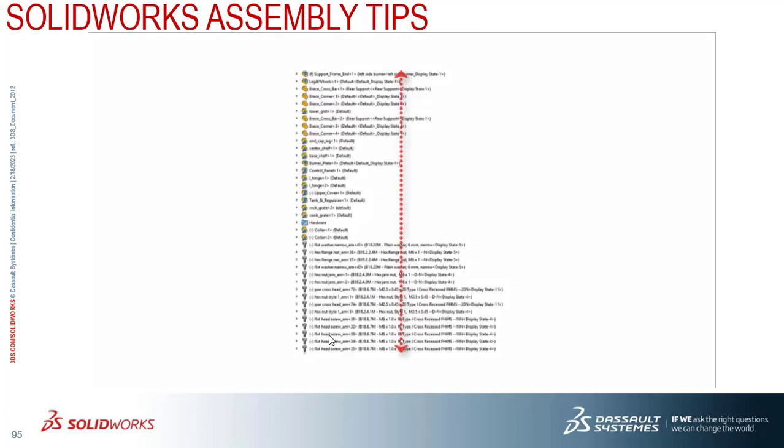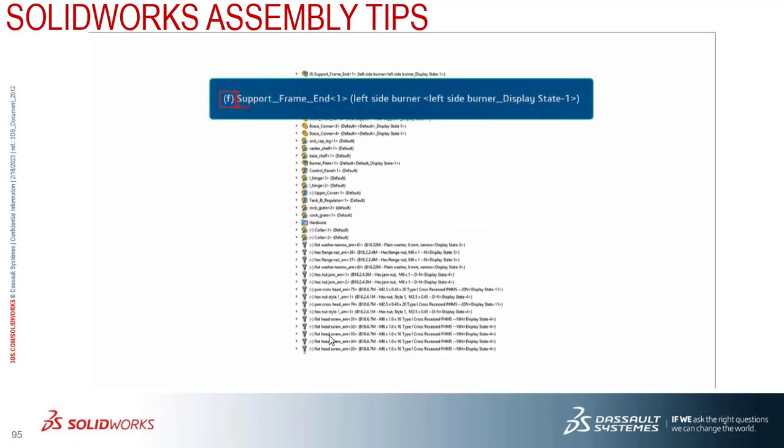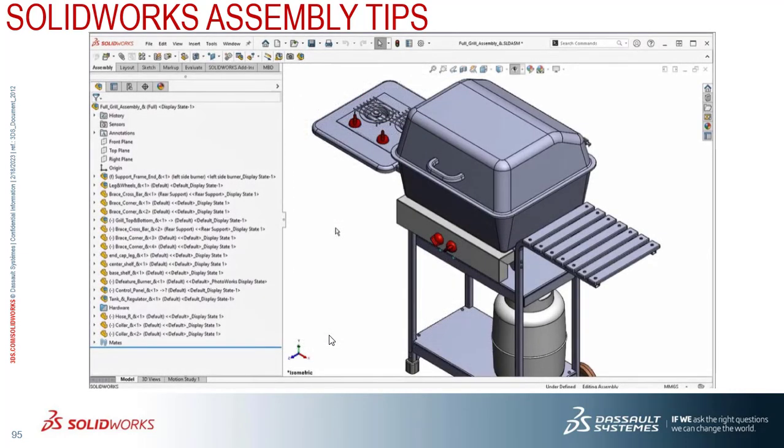If your assembly feature manager design tree is very large and very wide, you can also optimize that. For that purpose, you have to analyze the data: the part file name, then the instances that we have put into the assembly, then the configuration name, and this is the display name. So this is the nomenclature. We have to think about what we need to see here.